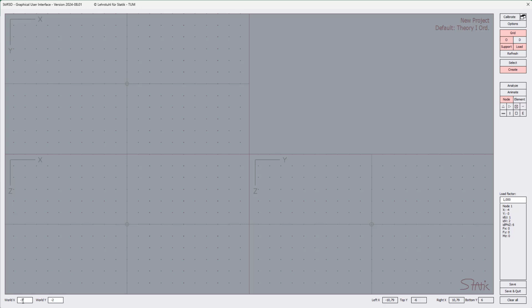X to the -3. Then again, pressing the tab key, the cursor is hopping into this Y cell here, World Y coordinate. Let's put it also to -3, and again typing the tab key. You see, the display has been modified from World Y to World Z here, and here from World X to World Y. That is still okay.